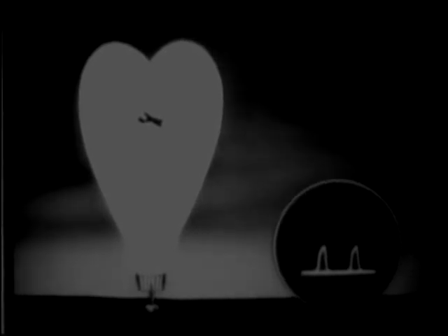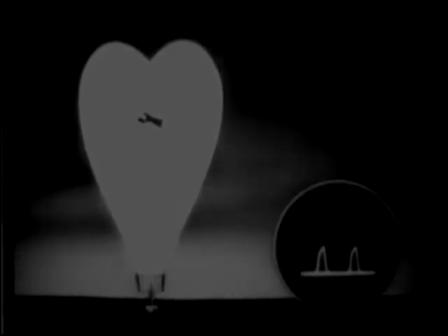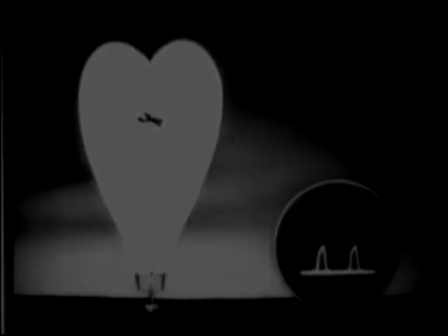To remedy the weakness of the single lobing system, we switch this single lobe back and forth so fast that you have virtually two identical lobes. When you have a target, these lobes are represented on the scope by two separate pips, one for the right lobe and one for the left. When the target is centered between the two lobes, the pips balance. That is, they're the same height.